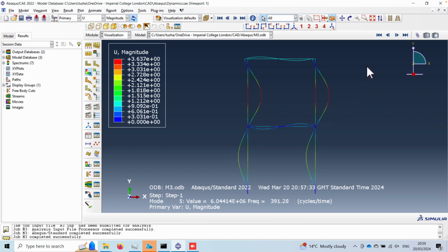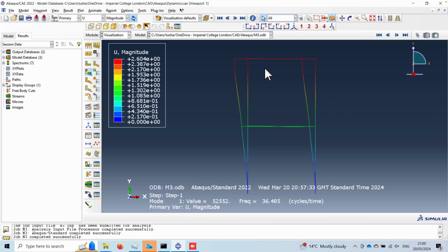And here of course we cannot compare with the analytical solution, but we can get some idea of different modes, right? Different mode shapes and corresponding frequencies. From the frequencies you can understand that the high frequency modes will not occur very usually. Of course the first mode you can observe very naturally. Second mode, yes, but for the higher modes the frequencies are quite high.